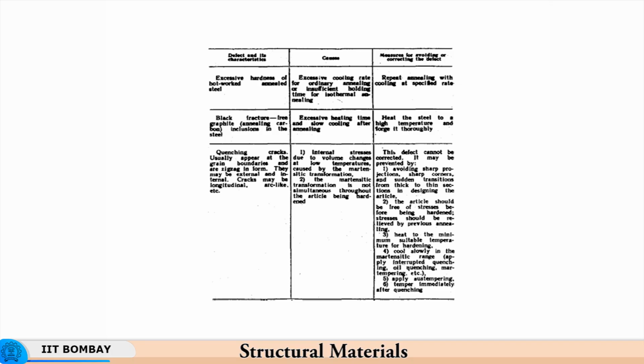So it is important to have some design considerations, design for heat treatment, where you avoid sharp corners, and you avoid sharp or very abrupt transitions, heavy transitions from very thick to very thin. The transition being abrupt is one thing, but large transitions from a diameter of, let us say, 50 mm to 1 mm, or 100 mm to say 10 mm, are also very large. These large transitions have to be avoided, so that the cooling rates are more uniform and the microstructural changes are more uniform.